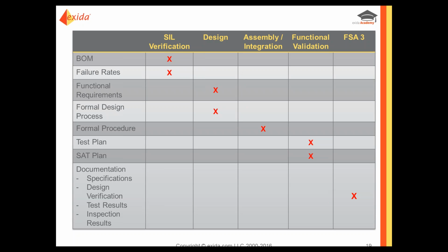Are they safety critical or not? And if they're safety critical, what are the functional failure modes we're worried about? For example, there could be a quick exhaust valve, but if it's just there because it's nice to have and you'd like it to close sooner, but you don't have to for safety, then obviously you wouldn't include it.